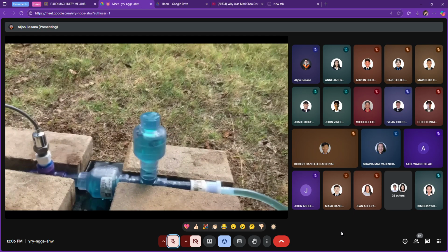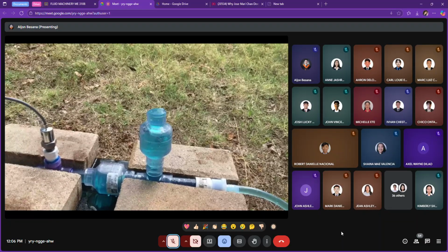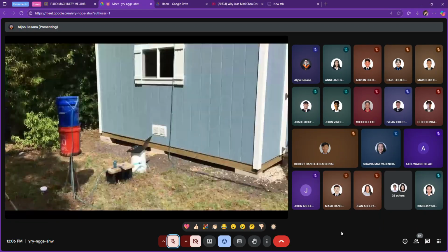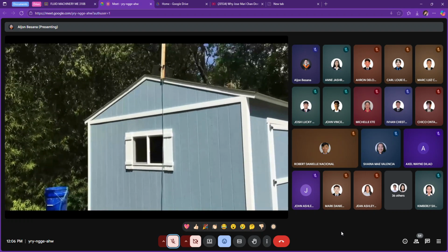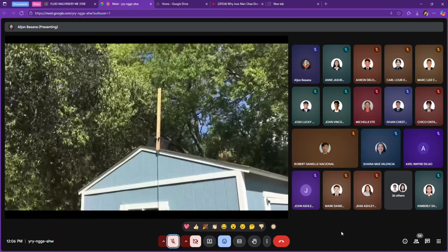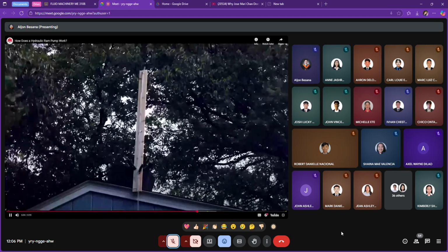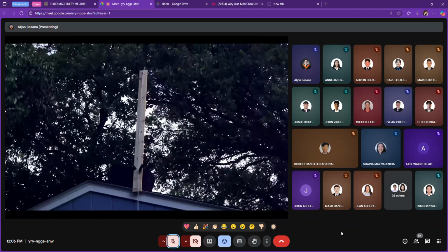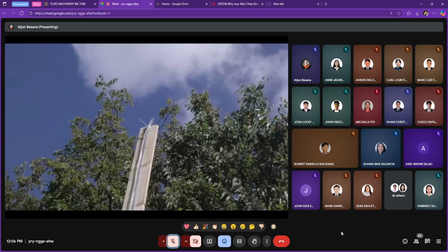The pump is robbing some of the kinetic energy from the flow and imparting it to a smaller volume of water. It's a redistribution of energy, converting low head and high flow into high head and low flow. And this type of pump can really create a lot of head. I ran my discharge line up to well above the roof of my shed, and my pump is still able to get the water up there.